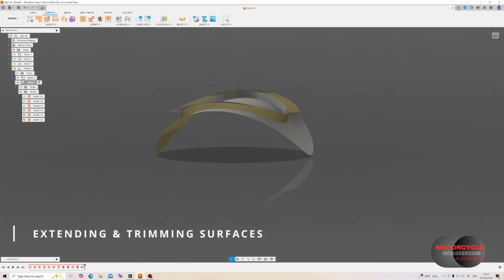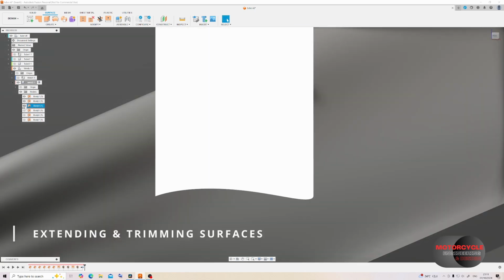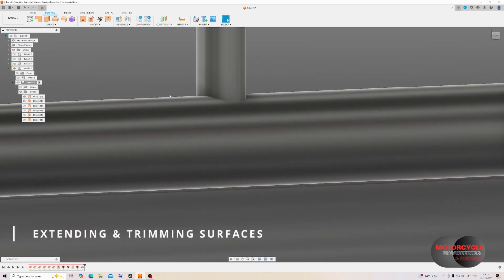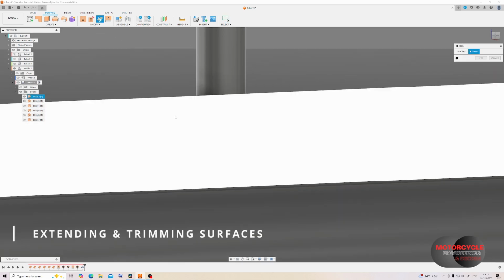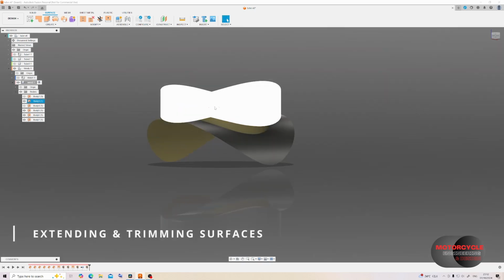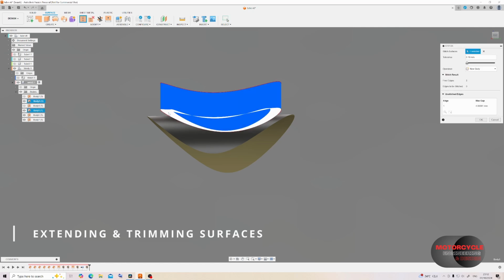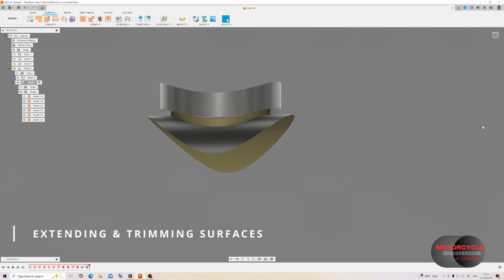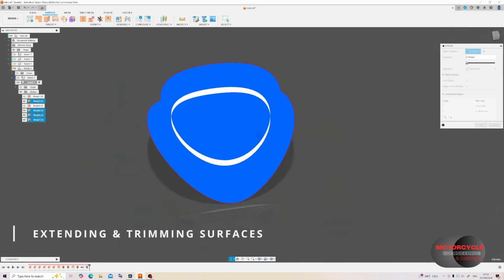So whilst I'm making a mess of this, I'd just like to explain a couple of points about these models. These are just being used for this example. If these were going to be real tubes, there would be a number of extra details that you would see here. And perhaps I'll include that in another video before we go more into depth on the actual frame design. But the kind of details you could expect would be those required to produce and manufacture the tubes, those to secure the tubes in a fixture, to control the tolerances, to provide drainage, and other details that have to ensure that we get good weld quality.